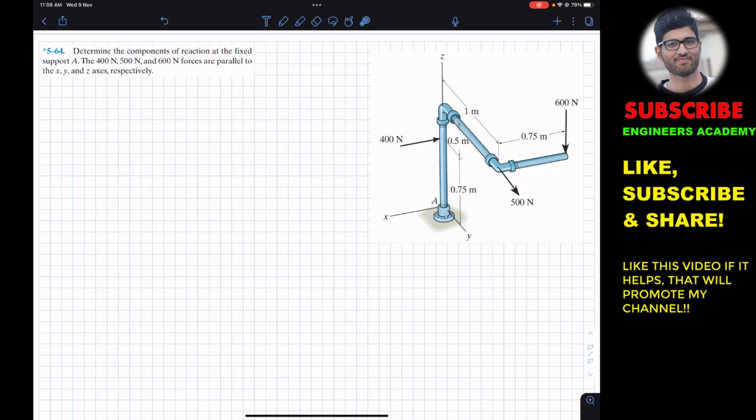At a fixed support, the support can always provide the force reaction in all directions, and it can provide the couple reaction about all the axes. So let me represent all those reactions. Let's say that at A, in the X direction we have AX support reaction, then we will have AY, and in the positive Z we have AZ,